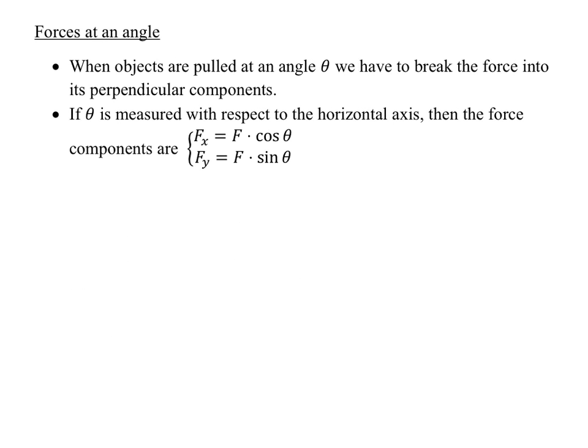We talked about forces acting at an angle. We need to remember this. Remember last year when something was at an angle, we had to think about the x and y components. X was cosine, y was sine. It's the easy way to remember it, if you remember from physics. So I'm talking about this. Imagine here's the node itself, and a force is applied at an angle of, let's say, 20 degrees, and it's a 50 Newton force. By the way, I'm going to finally go to pound forces this year because in the US we're going to use pound forces. You don't actually use newtons.